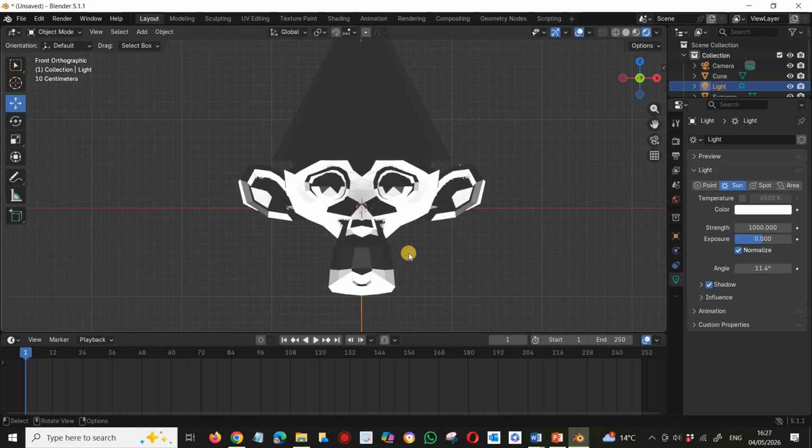If you can't see the shadows changing, double check that you're still in rendered mode, and then use your viewport widget, that's the coloured circles in the top right, to rotate the scene and check that your lighting looks good from every angle.